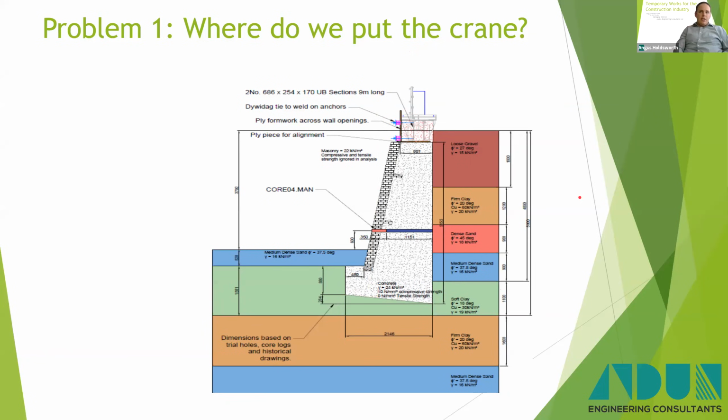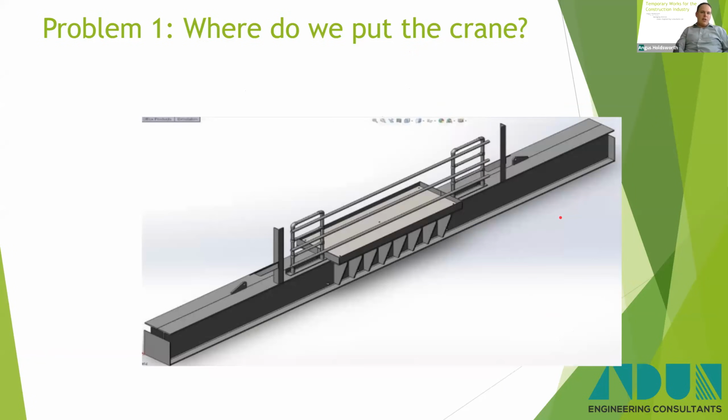So we designed these beams that went on the top. Now the reason they're so long, given the masonry wall, is that the construction of the wall was such that there were joints at regular centres along it, so we weren't sure that we could spread the load along it. So that's why we put a steel beam on the top here, with the outrigger in the middle here. That thereby ensured we mobilised sufficient length of the wall that we'd be sure that we weren't overloading the wall in bearing.